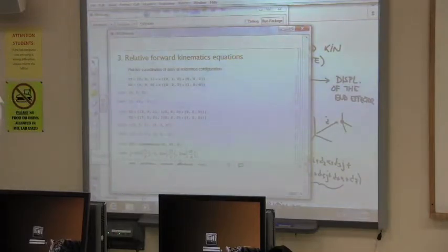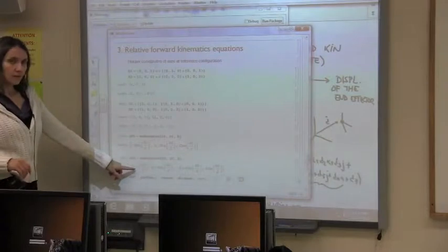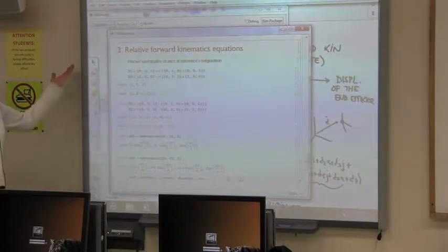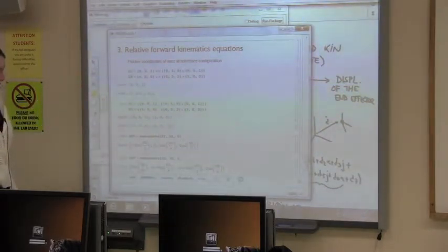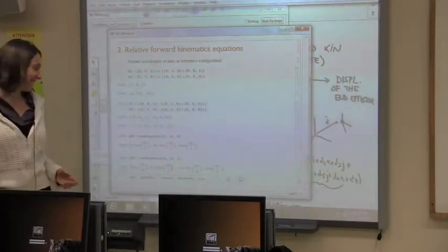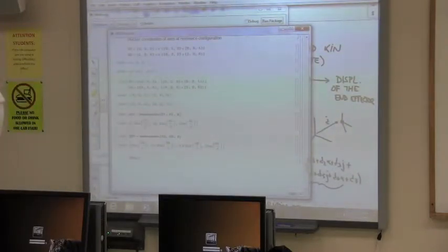And then we can do the same thing for QS2. Make quad S2, the line, the angle theta 2, and then the slide, which is 0 because it's another revolute joint, and this is a rotation about the second joint axis. And we multiply this and we get the forward kinematics. You see, it's easy. I'm trying to sell it to you guys. I'm a salesman for Clifford algebra. I'm a saleswoman. So now we can do the forward kinematics. FK rel is that easy. Quad mult, QS1 and QS2.